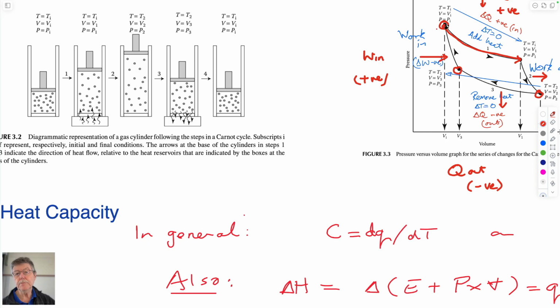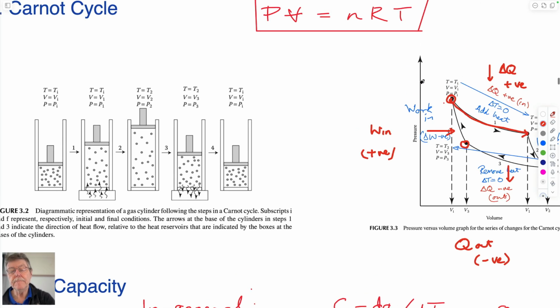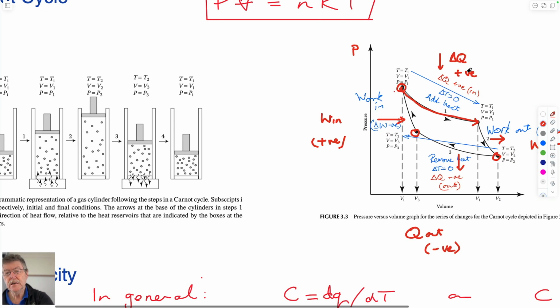So we did it before in terms of a phase diagram for water. This, in our previous case, was temperature rather than pressure. Here we've defined it in terms of pressure. And so this occurs at no temperature change. As you remember, we went horizontally. So no temperature change, but accepting heat into the system to change its enthalpy, then allowing it to expand, using that expansive power to do work.